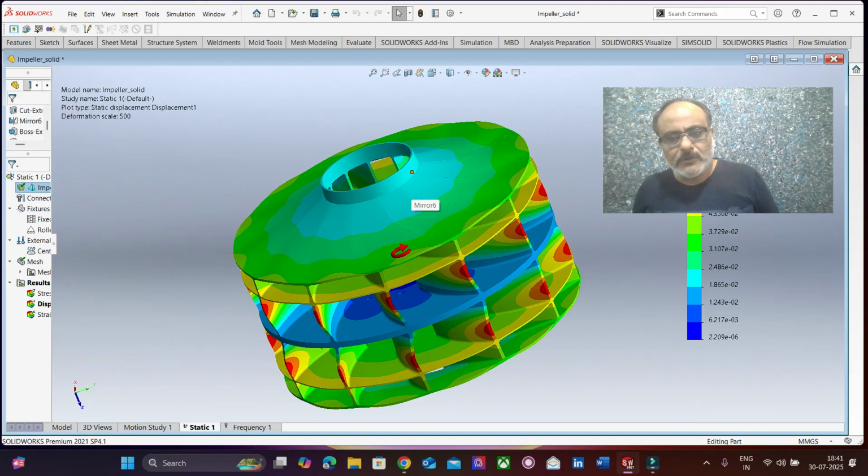The shaft is rotating, and there is a blob of air stuck inside the impeller, which is going to be radially thrown out. In that procedure a torque is induced, and this torque creates a torsion on the structure, and to reduce the torsion we have the crown designed.